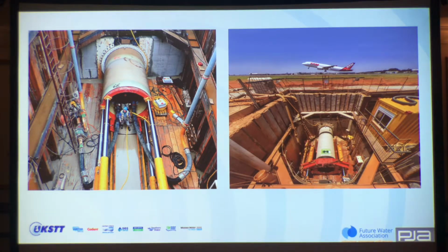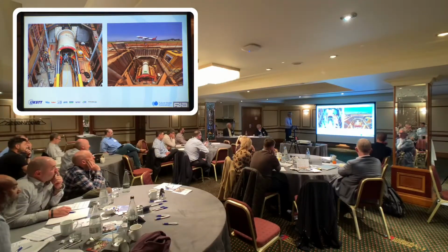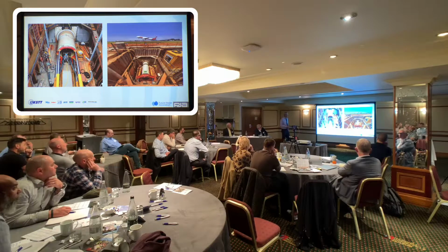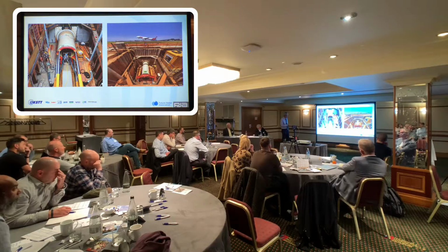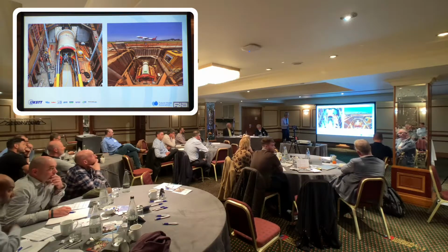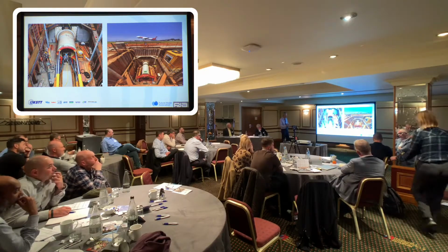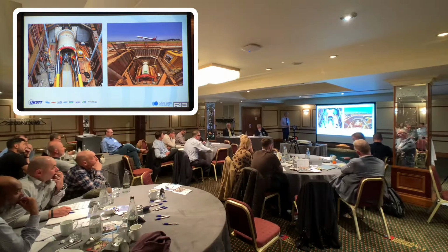And these are again just a couple of photographs. This is another picture of the same ram set in a different shaft, I think. And one of the things we've not spoken about is the entry eye. So like the sheeted pit needing to be sealed, at the junction between the pipe jack and where it exits and enters its reception shaft, there needs to be a seal.